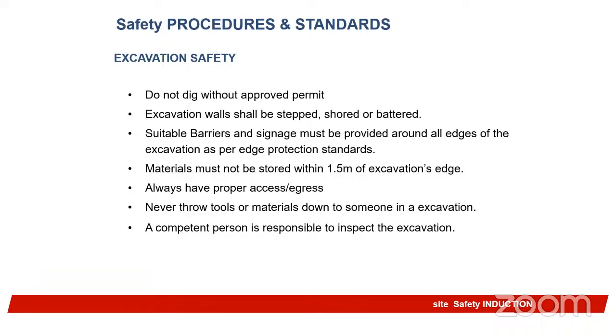For example, for someone that wants to excavate, whether manual excavation, deep excavation or shallow excavation, or using an excavator, no matter what you want to use, there should be procedures, and you tell them these procedures. Do not dig without approved permits. That is the first thing. There should be a permit to work that has been signed by the manager, the engineer, the supervisor, the permit authorizer.